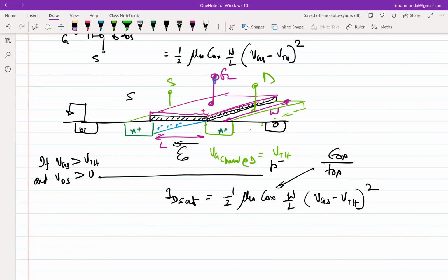What about threshold voltage? Kind of fixed. We'll see later on, you can change the threshold voltage slightly in some ways, but for most practical cases, threshold voltage also doesn't change significantly to cause a lot of impact. VGS clearly is in our control because we are applying the gate voltage, we are applying the source voltages.